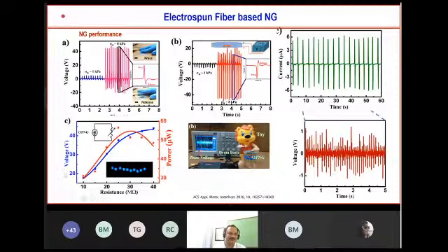And this is the famous power curve. Here we use our nanogenerator with an external resistance, and we record the voltage. You see that at a particular resistance the impedance is matched, and maximum power transfer takes place, and we get the maximum power. We know that when the internal resistance equals the external impedance, we can get the maximum delivery of power. So this is very important in order to make the device. And you see there, this small mechanical impact can even light several LEDs in practice.